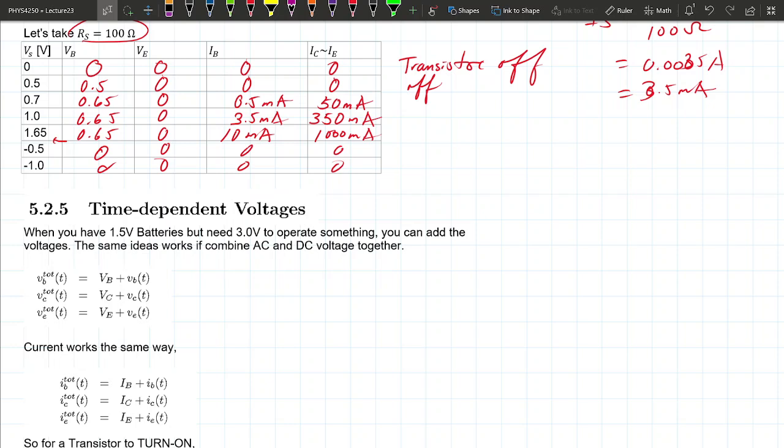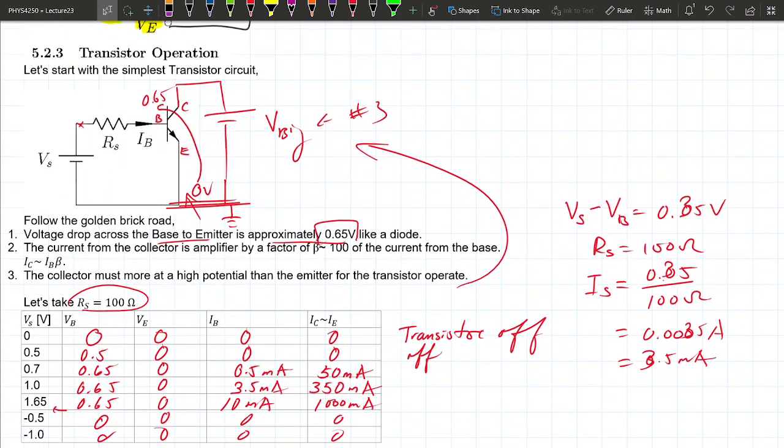If you want, you can go into your kit and take out one of the transistors and look at it. It'll be one of these little black things with 3 legs. In the 4th lab, it'll tell you which one is the base, which one is the emitter, which one is the collector. Usually the middle pin is the base, and one of the other pins is the collector, and one is the emitter. Basically, you have a little circuit that you can plug in like this.